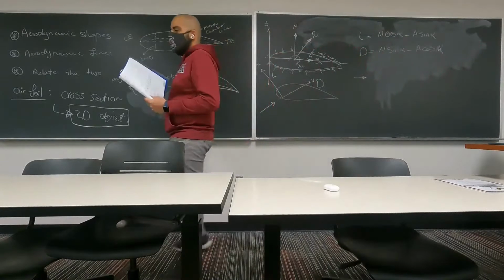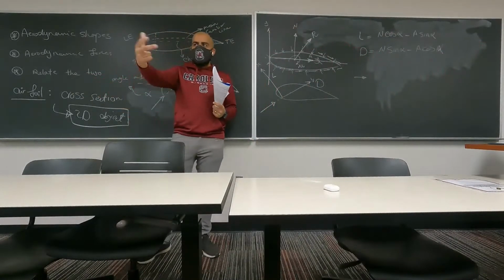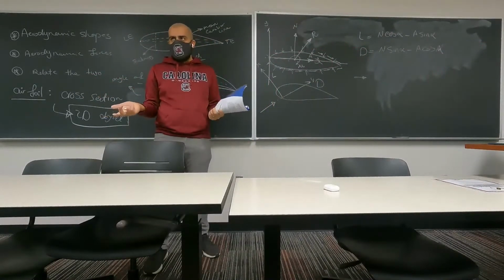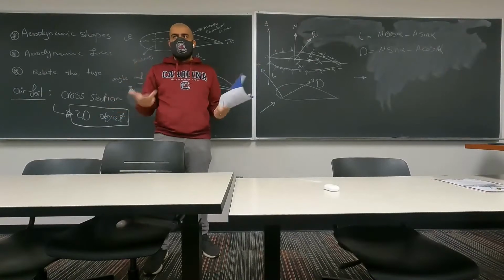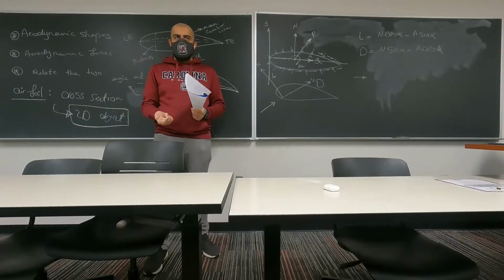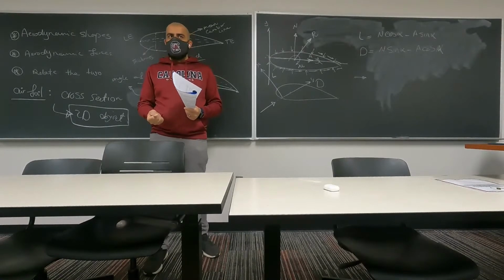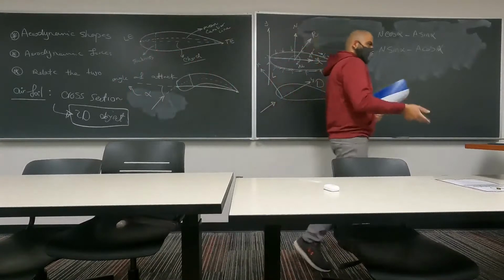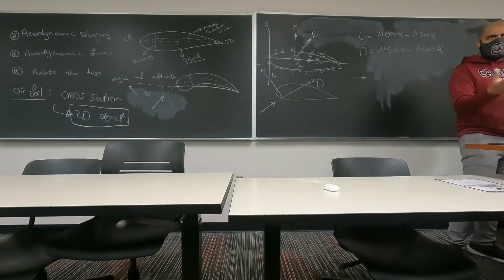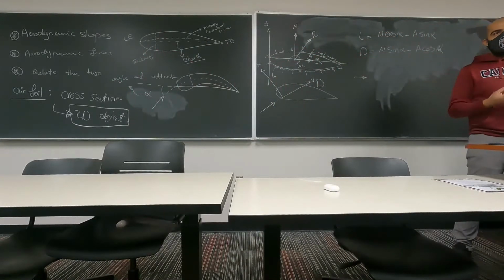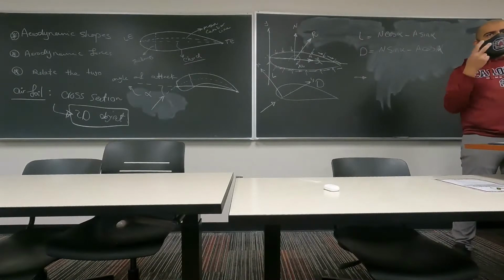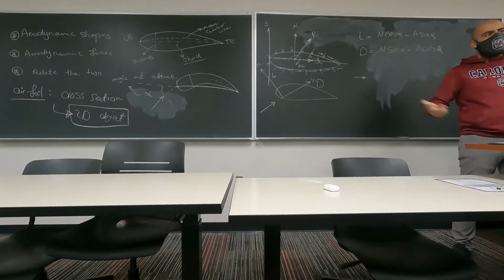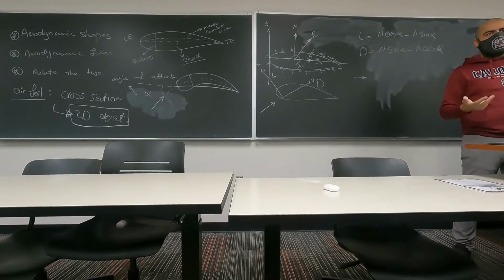But let me ask you this: why do we have dimensionless parameters? We are familiar with them, though, right? Lift coefficient, drag coefficient. Why do we have those? Exactly. To be able to test something in a wind tunnel, and we have discussed this in this class as well, and then apply the findings to a bigger scaled model of whatever you are dealing with, right?